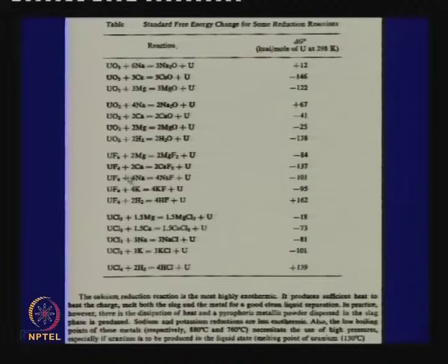From that we can produce a fluoride or chloride, and then we can think of reducing the oxide or the fluoride by some metal. There we have to take into account where the free energy change is more, where the exothermic heat available is more, and of course, the physical conditions of the reductant, product, etc.